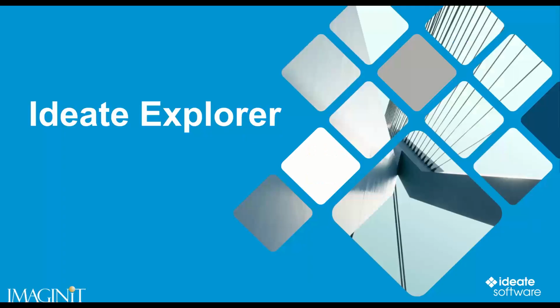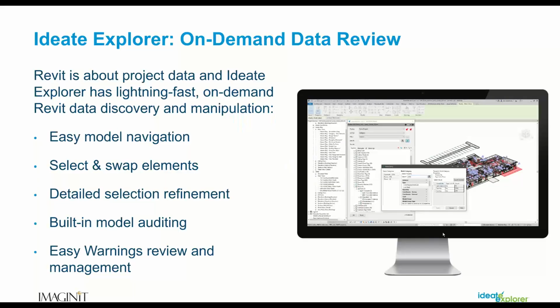So with that, let's get into Ideate Explorer. There we go. Ideate Explorer, believe it or not, is one of my favorite tools that I use on a day-to-day basis when I'm doing production work or BIM management services. It allows me to navigate my entire project live or on demand. I can have it up and going as I'm working around doing my health checks or looking at things. It's an easy way of selecting and swapping out elements.